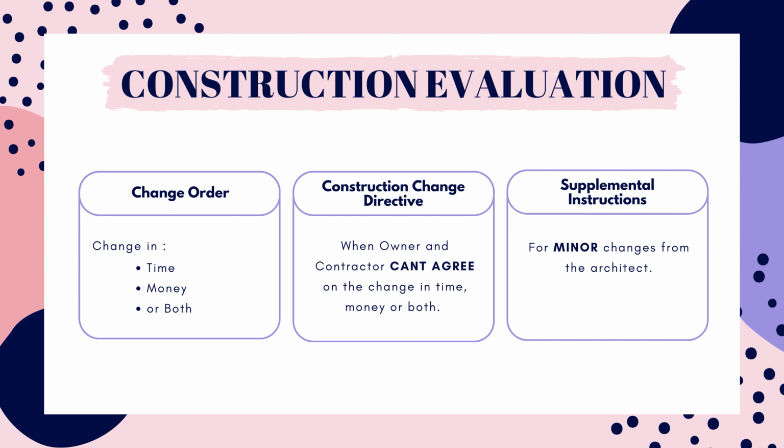in the contract. In the scenario described, where unforeseen soil conditions require immediate excavation modifications, a change order is the appropriate document. This formalizes the changes, outlining the increased cost and adjusted timeline, and ensures that all parties involved are in agreement regarding the alterations to the project scope and contractual items.